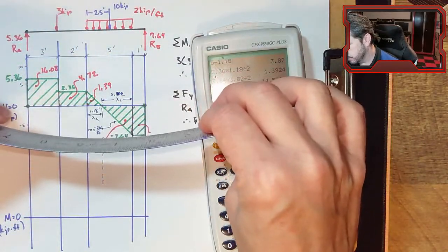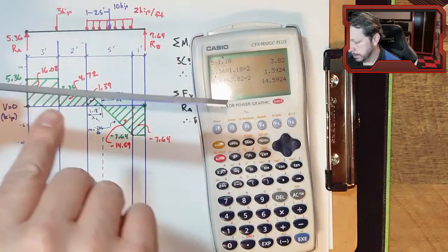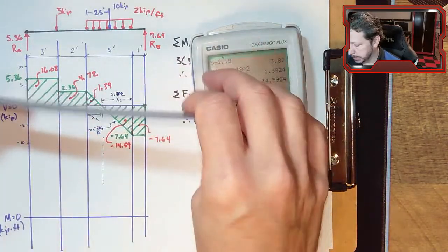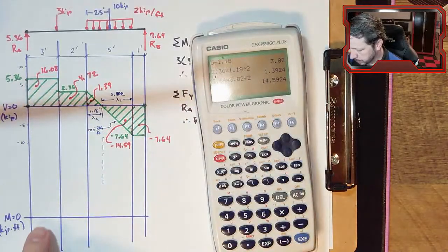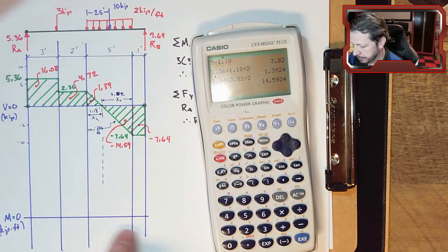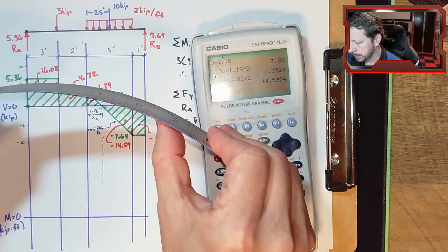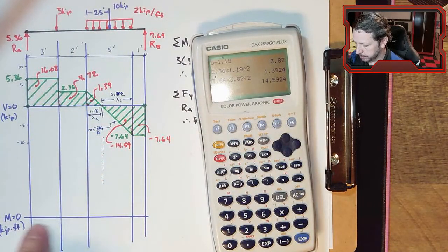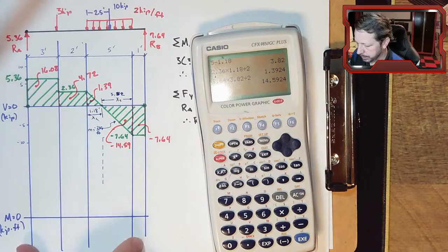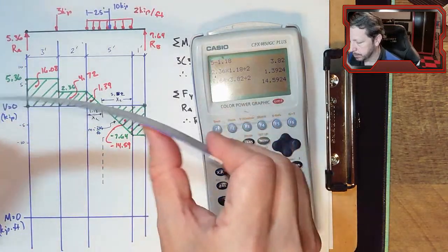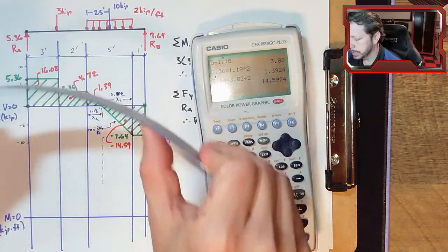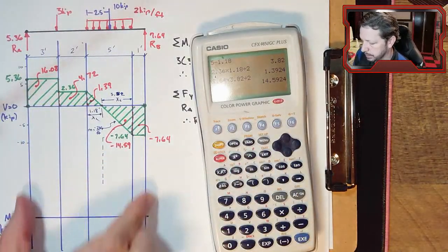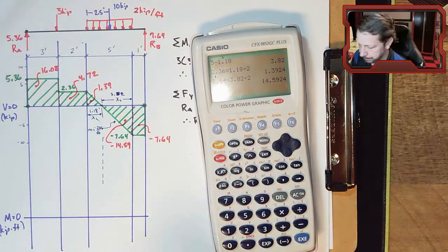So if that's true, then that's a positive bending moment when tension's on the bottom. So I'm pretty sure there's no negative bending moments, nothing that's causing the beam to bend with tension on the top. So I can move the reference pretty far down to the bottom. If I thought there were sections of the beam where it had tension on the top, then I would move this higher up so I could draw down beneath it.